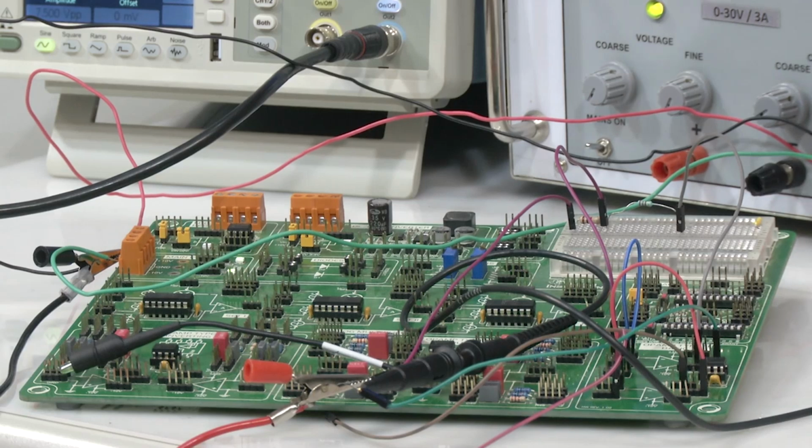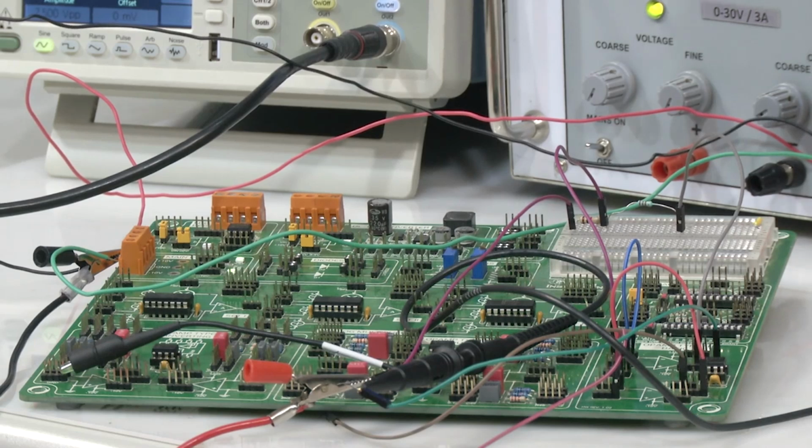That is what we will see now in this experiment, and we will see the same thing for a unity gain amplifier also, where the gain is lesser, correct. Accordingly, we should observe that the output remains faithful to the input for much higher frequencies. This is also an aspect of the range of a feedback amplifier. Here the range is the range of input frequencies which we can apply. In the first part of the experiment, we saw the range of input voltages that we can apply.